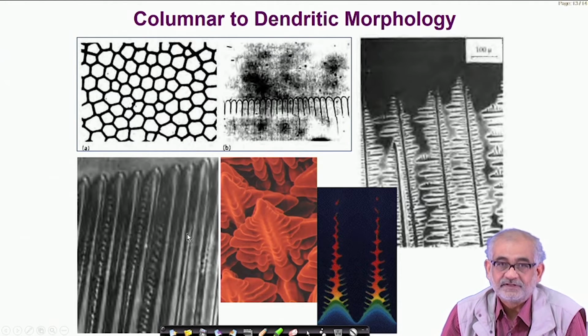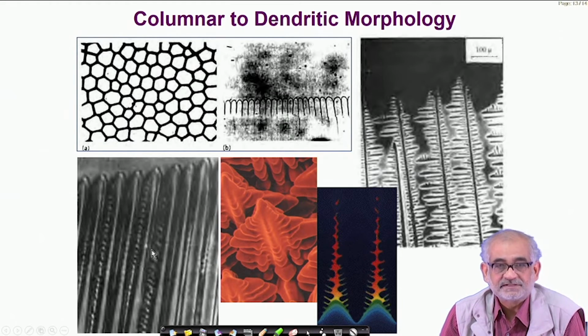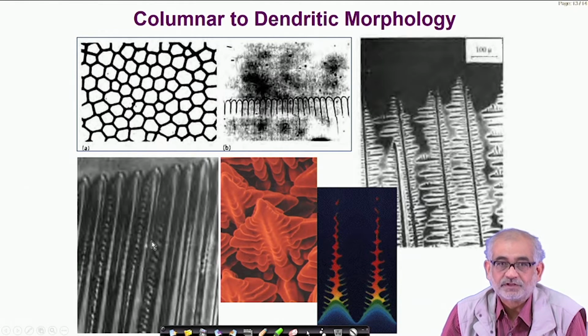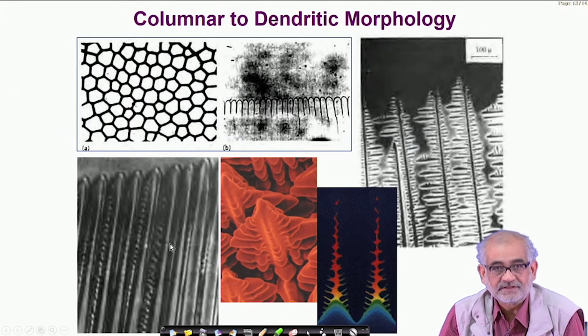But in between, from the core where we have equiaxed to the surfaces where we have chilled or ultrafine zones, we are likely to see directional solidification. And this directionality comes from the fact that heat transfer is across the mold wall, which could be the side walls or the bottom walls, and since the heat transfer is maximum across the wall, the growth front, which is essentially carried out through the solid liquid interface, will actually be in the opposite direction, exactly 180 degrees.